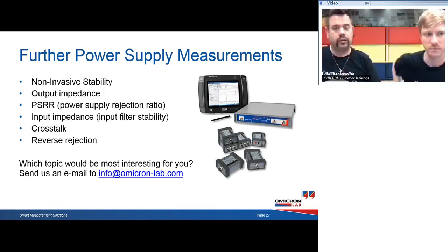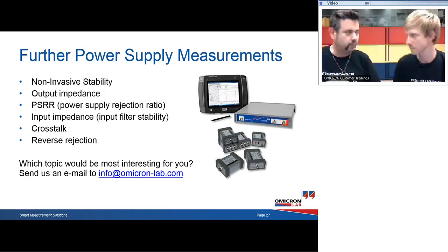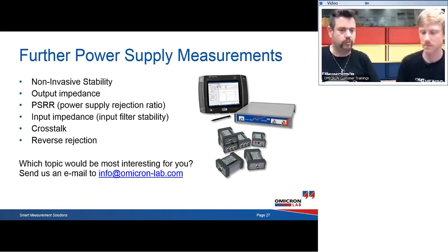Further on, we offer a lot of additional power supply measurements, like the non-invasive stability we will touch base on tomorrow, the output impedance, the PSRR, which is the power supply rejection ratio, where you can see how much of a ripple that is injected at the supply voltage of a power supply remains at the output of a power supply, or vice versa. If you modulate the output, how does it influence the input of the power supply, things like that, input impedance.